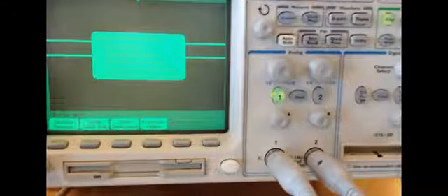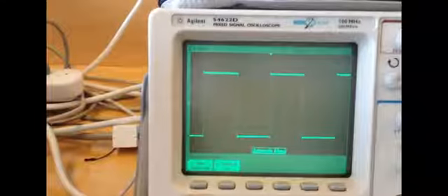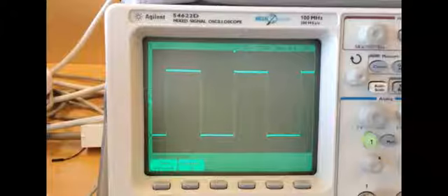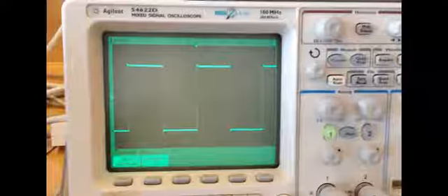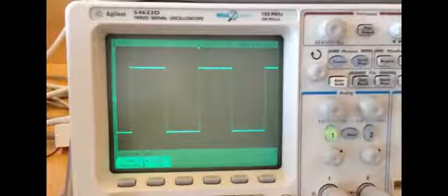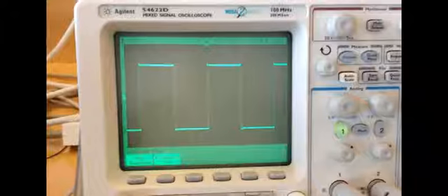Each channel has different knobs to configure the parameters, but the best bet from the very beginning to see the signal right away is to use a button that I normally call the magic button. It's called auto scale, which is this button. If I push auto scale, I'm going to see the signal right away on the display on the screen. So what auto scale really does is that it does all the configuration automatically itself, so it's programmed to do that.